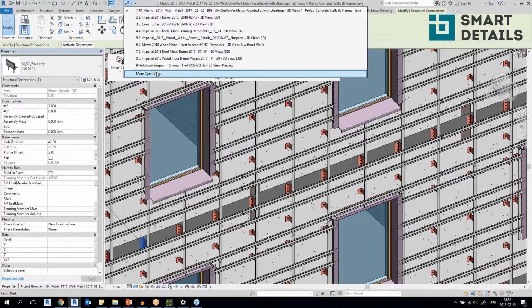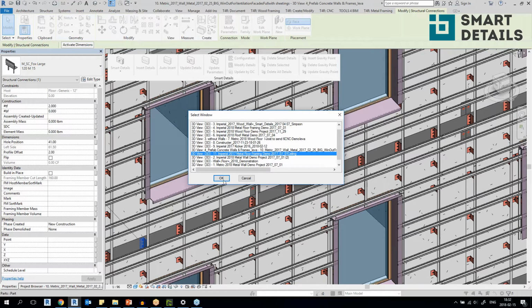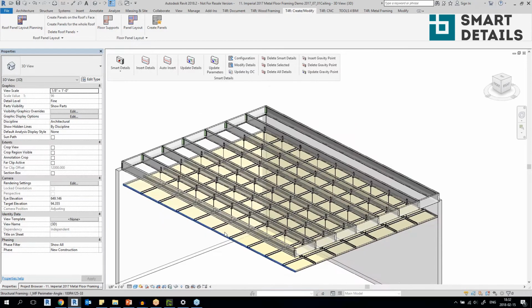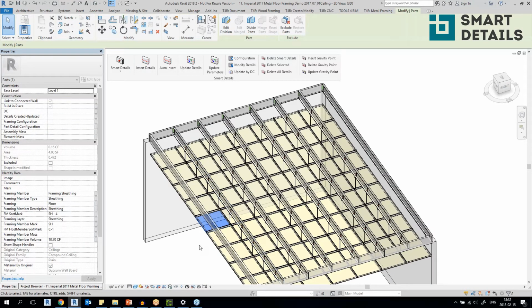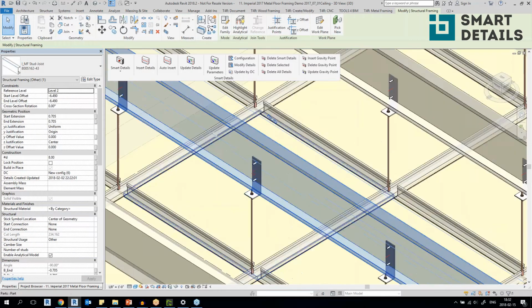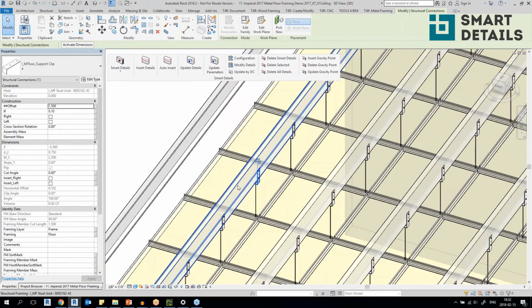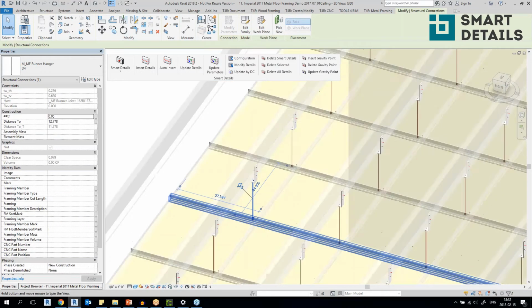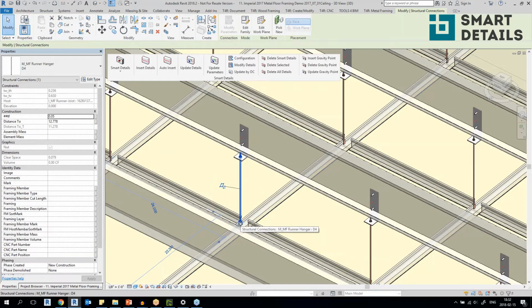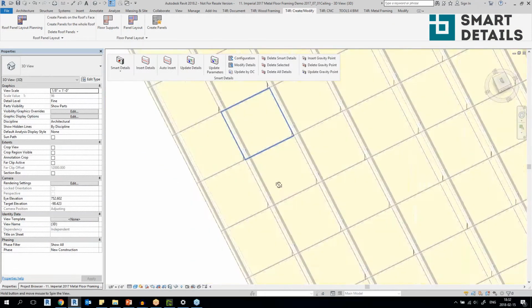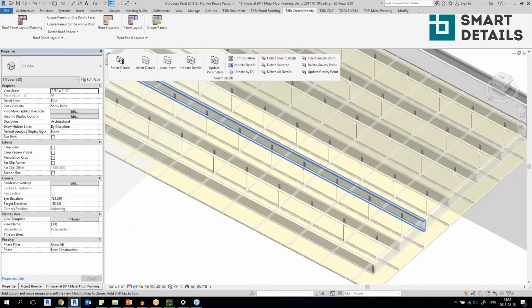We can also take a look at another project. Okay. And this is an example with ceiling. So you can see that the parts were split for the ceiling, also the frames were added using the framing software, and finally the details were added on the side face of this joist for stronger support. And these details were also added by a separate rule, and they are connecting the ceiling and this detail automatically. It's searching for virtual intersection. If it sees the virtual intersection, it's adding the detail.